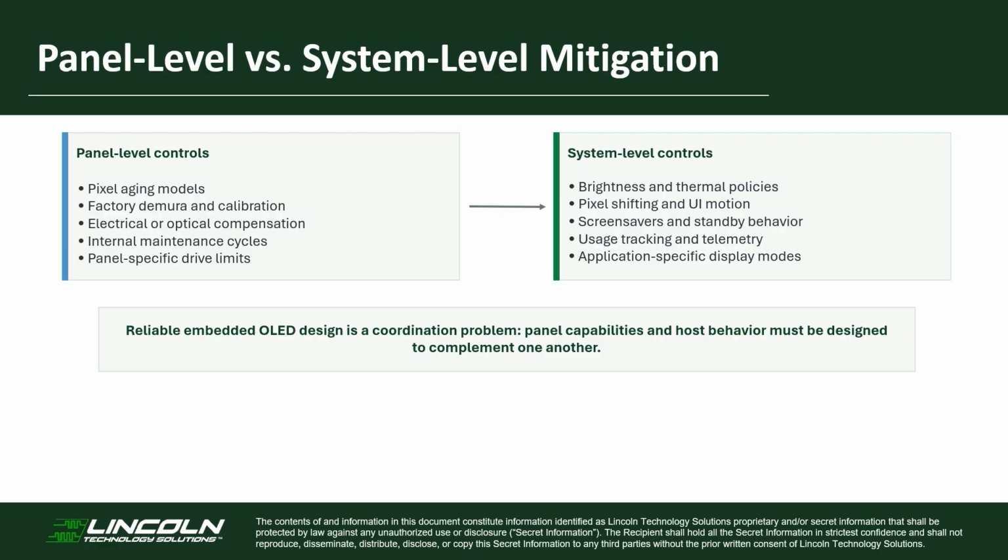These two layers are complementary. Panel compensation cannot fully correct for an interface that keeps a bright static element in the same location indefinitely. At the same time, host software can't replace the electrical and optical compensation built into the panel. Reliable embedded OLED design is therefore a coordination problem.